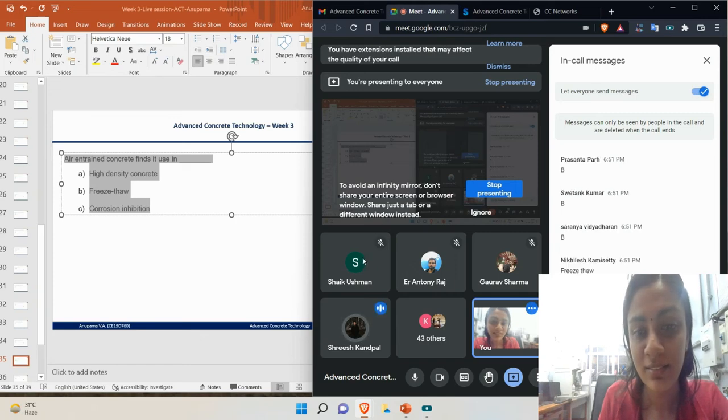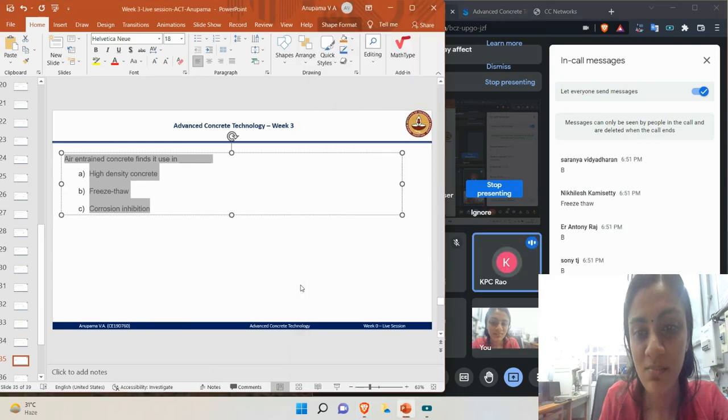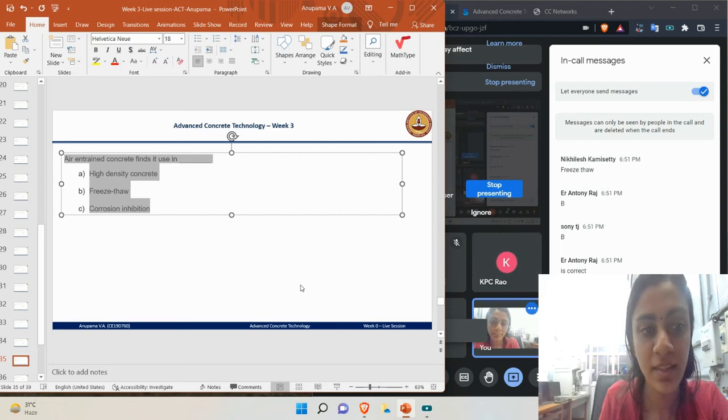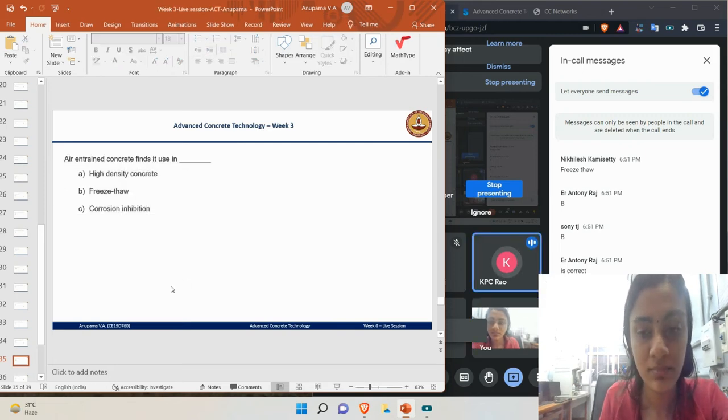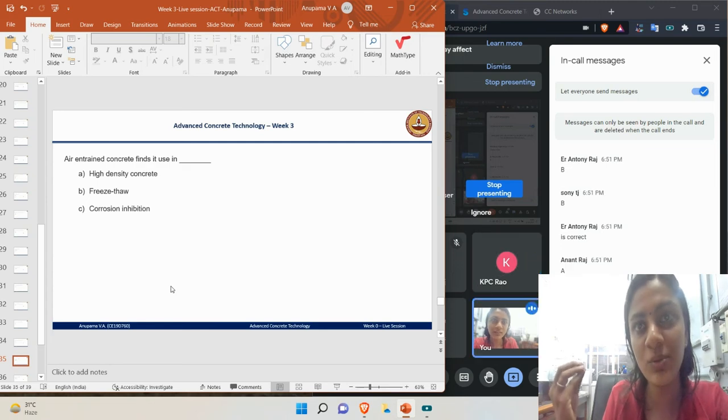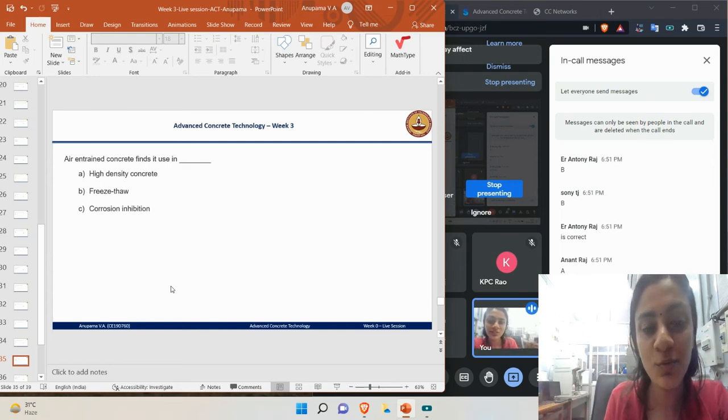For better ventilation. And also the water has to expand. In freeze-thaw conditions, the water has to have some space for expansion. So if these air voids are there, then basically to avoid any cracks, the water which goes inside the concrete can find some space to expand if the air voids are present. If there is no space available, it will try to expand and cause cracks.